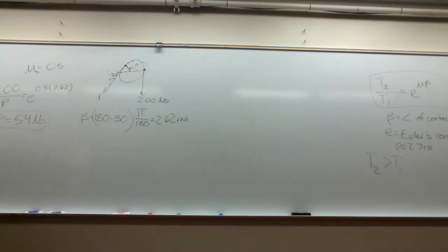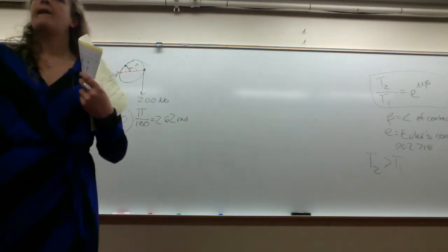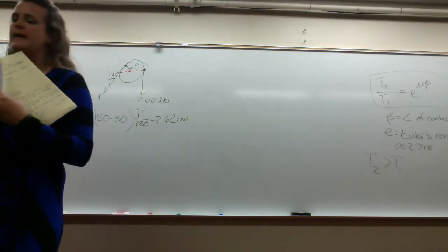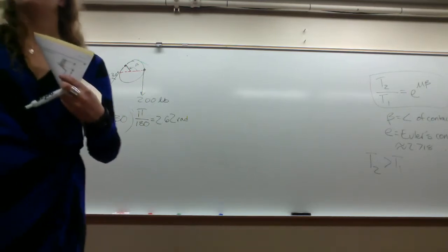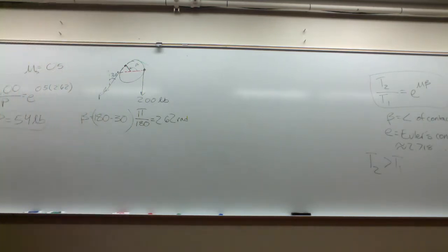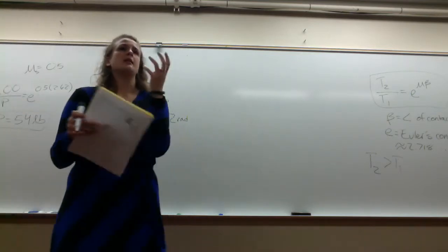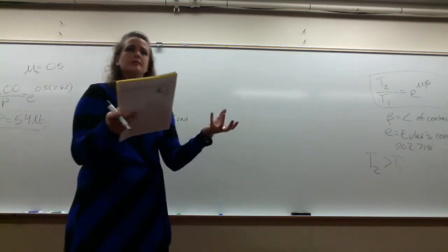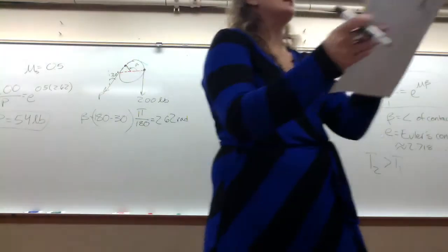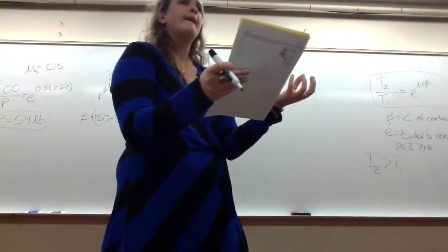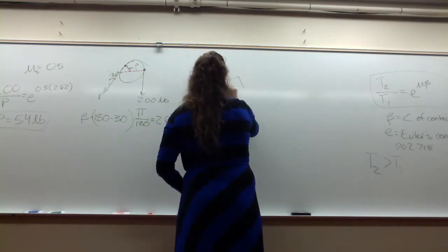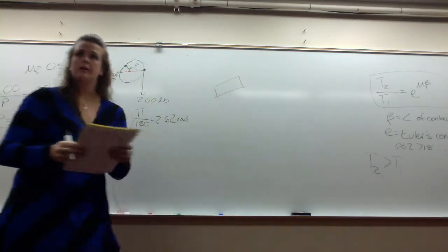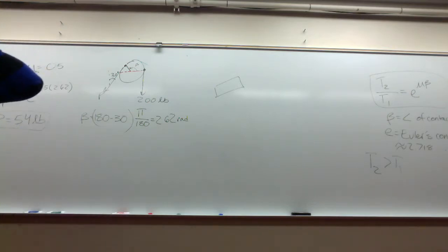So how do we solve machines? Analyze individually. What would you like? Jack's on a sugar high. Okay, analyze individually. Remember, typically start on a component that you have the most knowns. So what is that in this case? The log, right? So if we draw a free body diagram of the log, what are my forces on there?